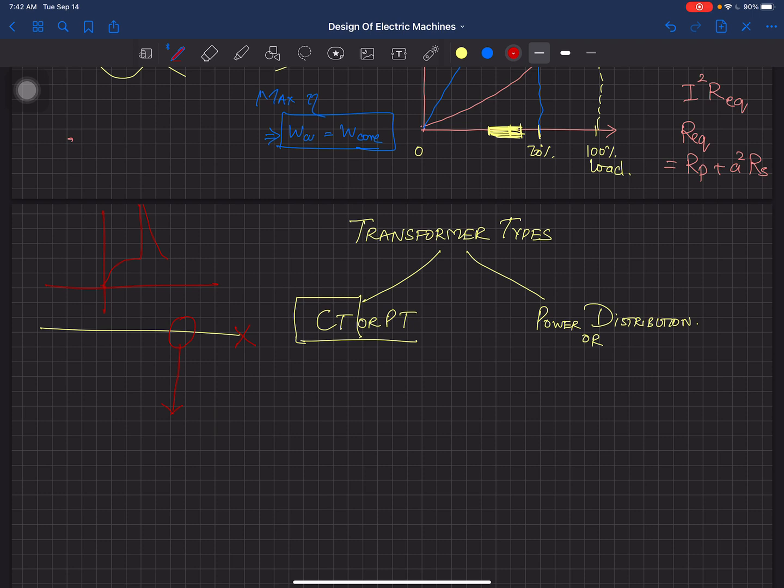But when it is going to come down, when you are actually going to break off that transmission line, how are you going to do it, because the CT has to actually detect it. So if there is a phase lag, it's not going to detect very fast. So it's going to have a very problematic or catastrophic problem. So the phase lag introduced by the transformer is very much important over there.